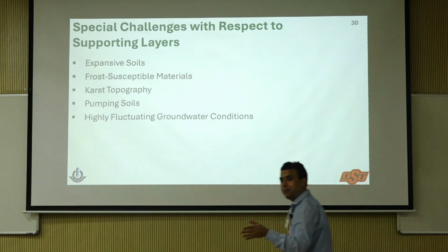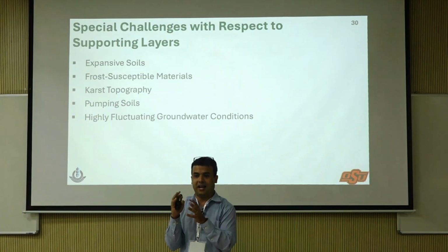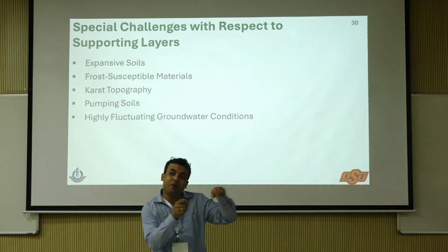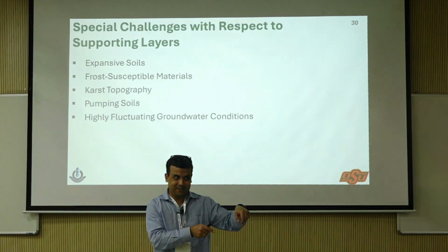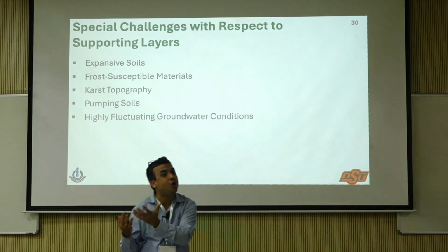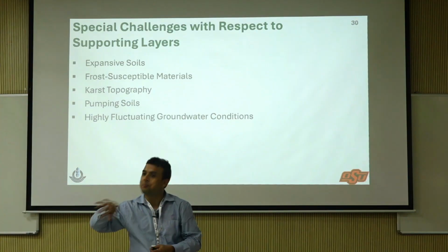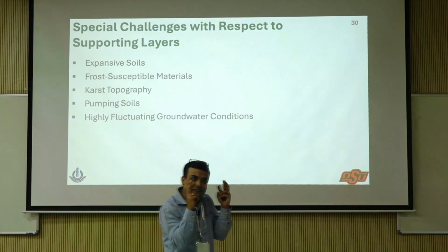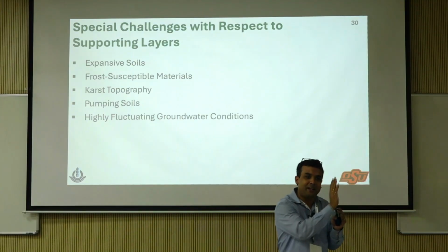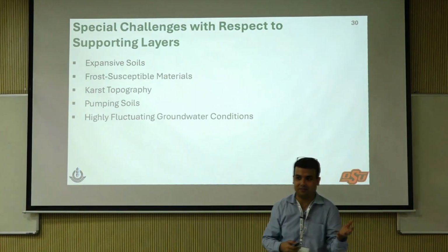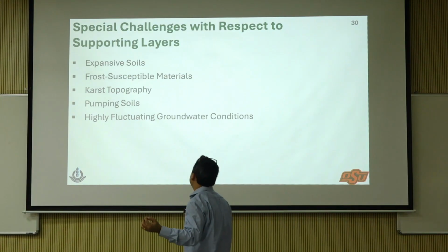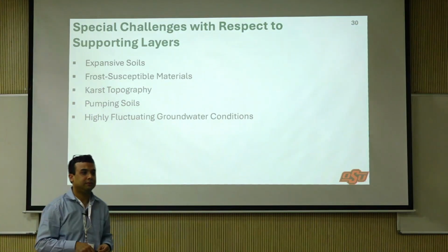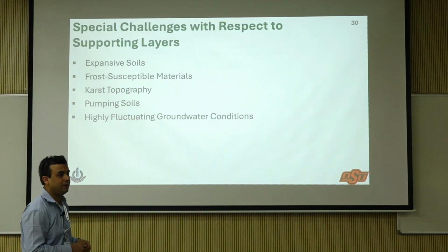The interesting thing is that freeze thaw and frost susceptibility are not as big of a problem on clays. It's actually a bigger problem on silts. You know why? Because clay has such low permeability that water does not even move far enough for you to have that problem. Silt has just the right combination, a little bit higher permeability so water can move, and it is still frost susceptible. So frost susceptibility matters. I don't think frost is a problem in Odisha, right? We barely get below, what, 15 degrees Celsius maybe, right?